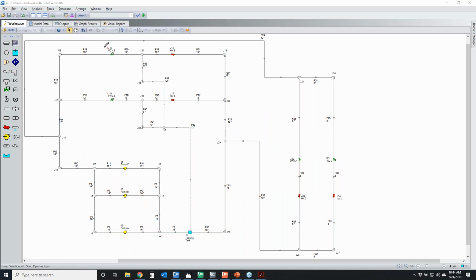And then I actually did a system where I'm pretending that these control valves here are failing open. When they fail open, these heat exchangers are going to see the full system pressure, which could be really high. If those are pressure sensitive, I don't want the high pressures to see those heat exchangers. So that's where I put in a relief line upstream of each of those heat exchangers.